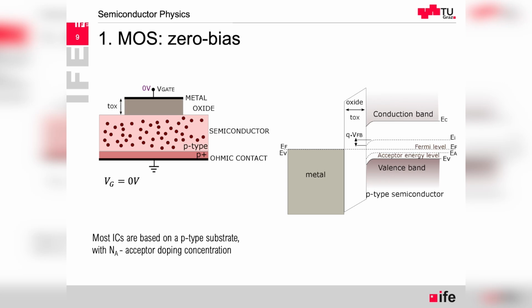So we have several materials, as you can notice in these pictures. We have the semiconductor at the bottom, then we have oxide, insulating, and then we have the metal or polysilicon gate material. Because of the different work functions, which we already looked at on the occasion of the metal-semiconductor junction, we see that every time, even for an N-doped, P-doped interface for a diode, every time there is a difference in the work function, there will be band bending.